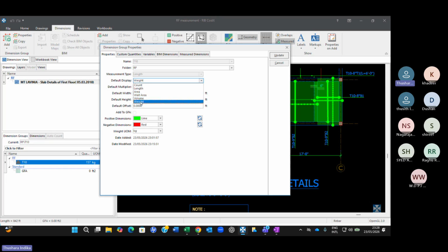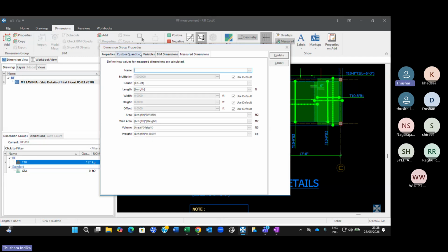Now you have just learned how to apply the weight. You have to give a relationship to this weight here, right, through a small equation. So likewise, you can give the surface area when you measure the ductwork, for example, right? You can give an equation so that you will see the surface area here, right? Even the formwork area you can introduce here as a parameter. So there are so many things you can do with this part actually, and this is called extended properties, right?